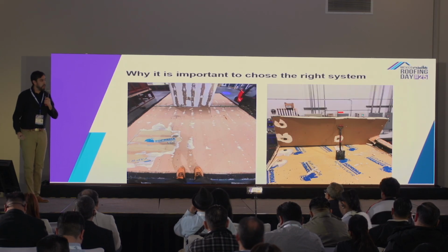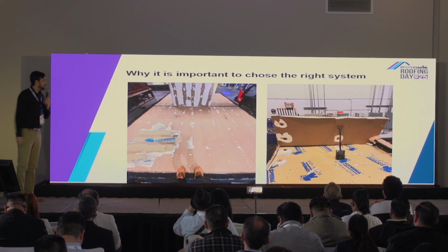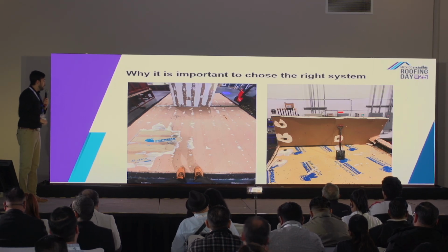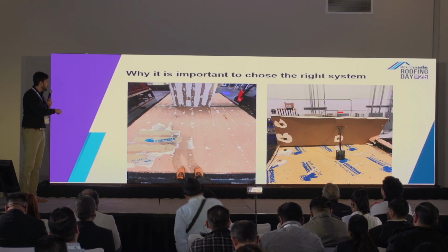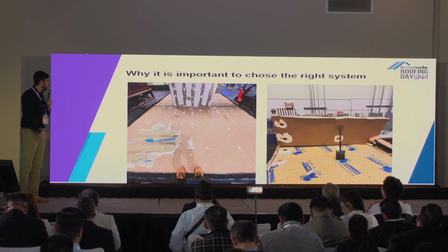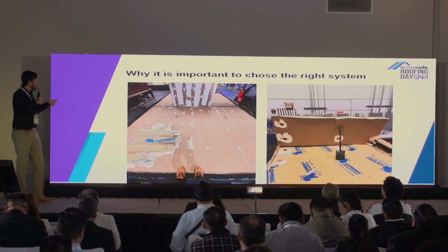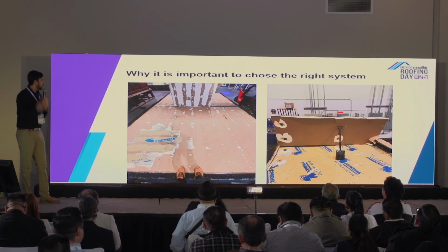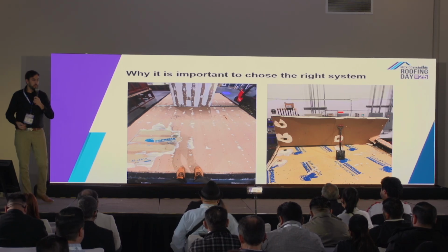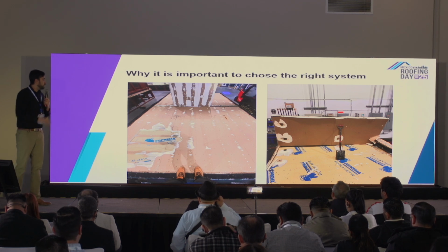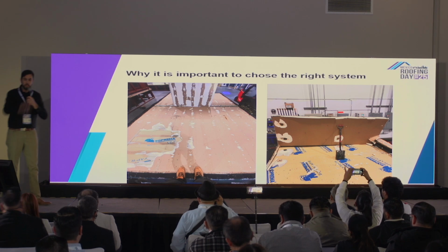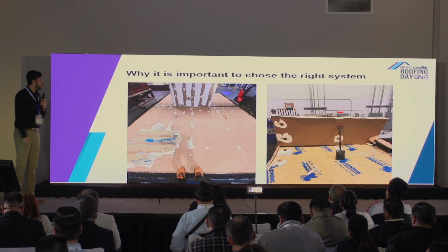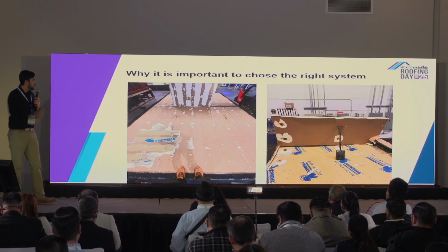So we're going to end this presentation with some pictures of when we're doing testing and the modes of failure that we can see. On the left, we see an adhered system, so no mechanical fasteners. We see the adhesive ribbons that are gluing down the insulation boards to the vapor barrier. In Canada, it's mandatory to have a vapor barrier on the underside or on the deck, as part of the building code. But again, not going into too much detail.